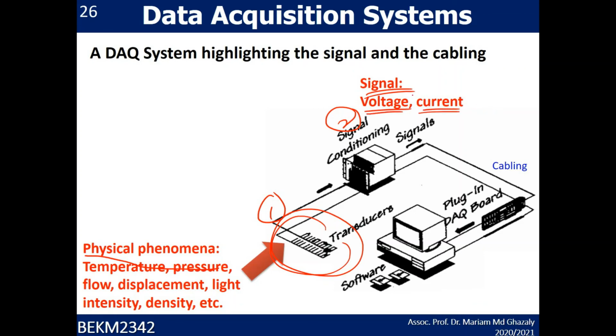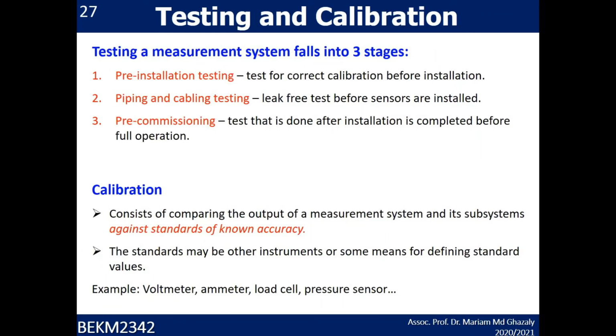Normally that is the signal that you are going to collect from the signal conditioning or from the sensor. Next is the cabling. As mentioned, make sure that the cable is well grounded, and that the amplifier, signal conditioning and filtering are well grounded. Lastly, connect it to the dashboard before you display it on the display unit.